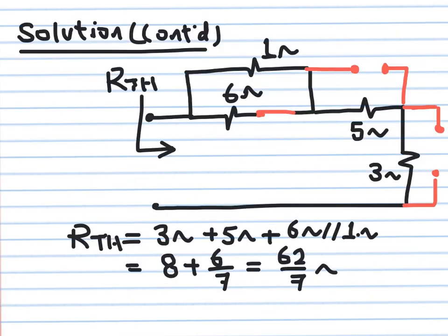Now we move to calculate the Thevenin resistance. One way of doing it is that you create a short circuit, but this is the first approach. Second approach tells you eliminate all the sources and try to calculate the input resistance seen between these two terminals, and this will be Thevenin resistance. So this is what I did here. As you can see, I eliminated the current source that was here, I made it open circuit. I eliminated the current source that was here and made it open circuit. I eliminated the voltage source that was here and I made it short circuit.